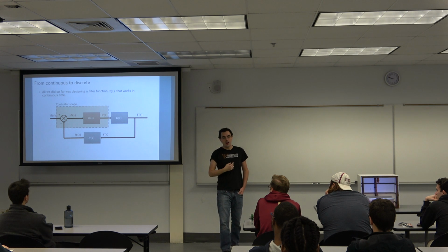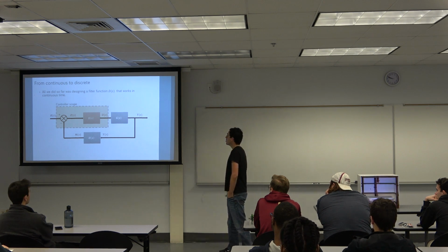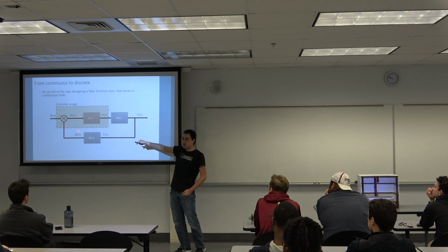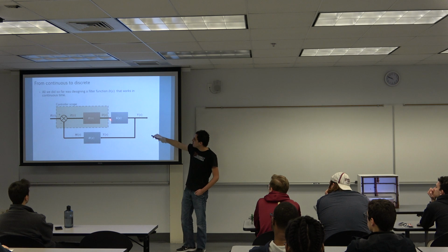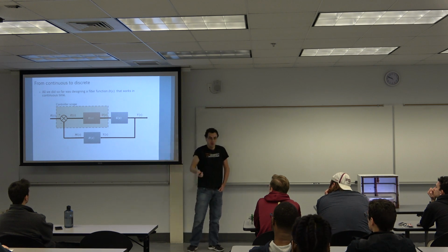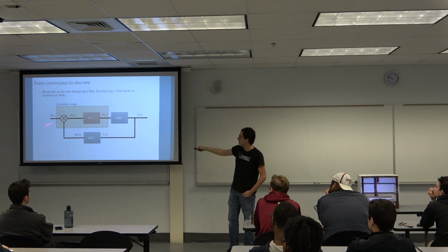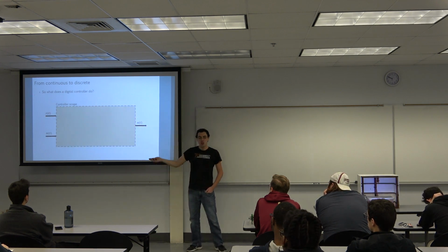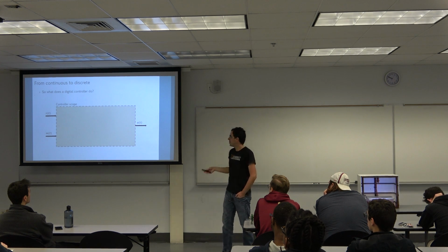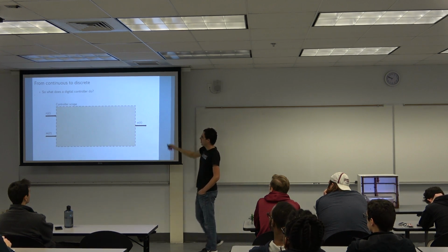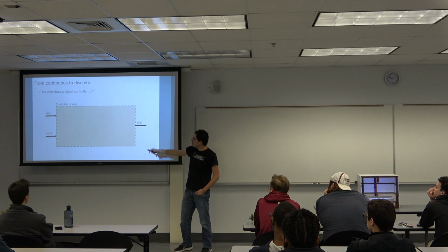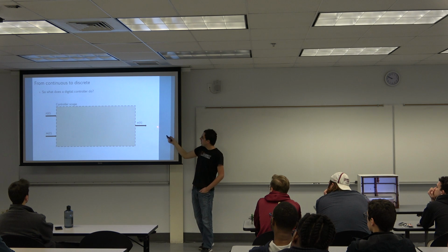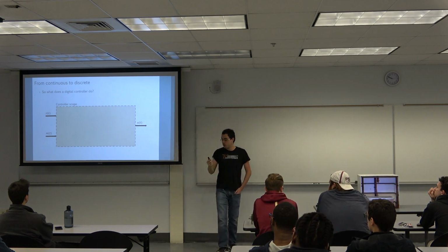And we want to know where our Arduino is sitting, right? So our Arduino is sitting in this box. So it's doing the subtraction operation, and it's also computing the control input. So let's expand it. And I'm going to shift here to time domain because frequency domain is kind of difficult to show the components inside the box. So we have a signal R of t and a measurement M of t. And we want to compute a control input U of t.